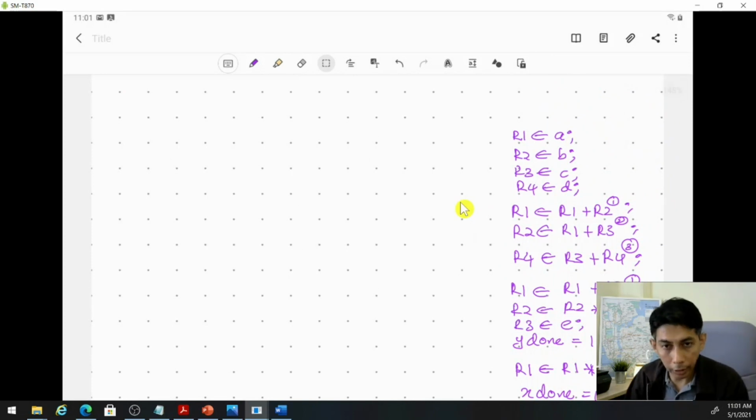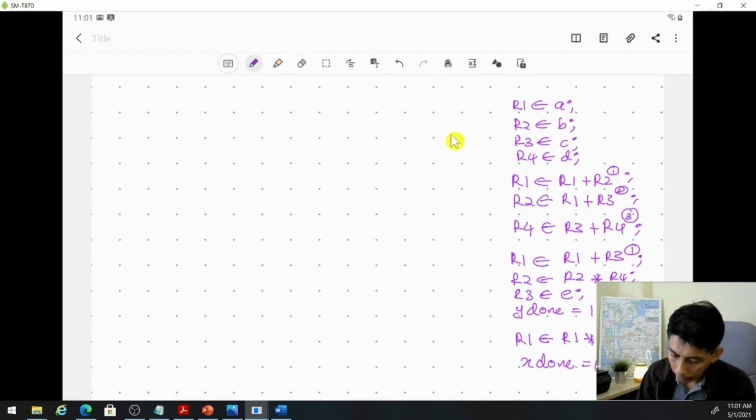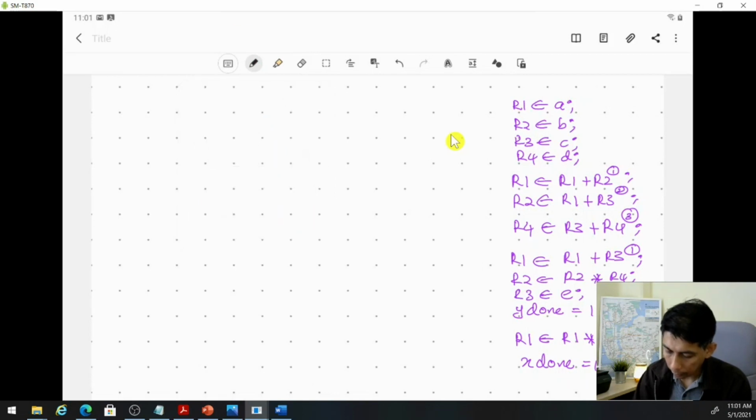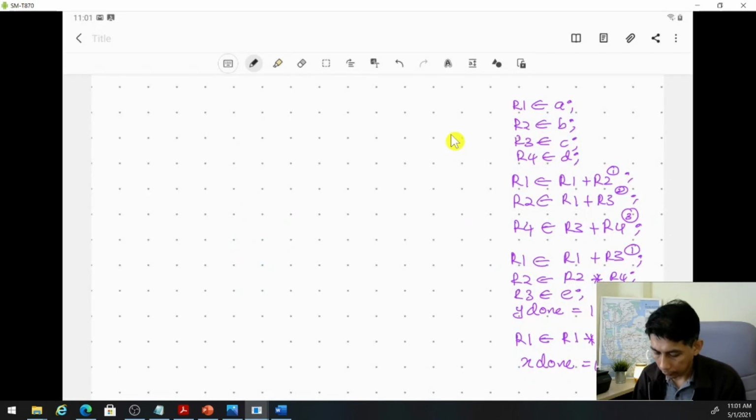From the RTL code, we can define the data path already. Here we can know how many registers we need. In this case, we need R1, R2, R3, R4, right? There is no R5 or any other register. So we have 4 registers. So let's draw 4 registers.